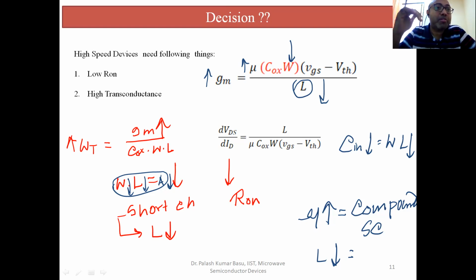And how to achieve the high frequency limit? You have to have a structure where you get a high mobility. But if you want a high mobility, you have to make sure it does not suffer any kind of collision. Very, very important. You need a high mobility where you avoid any type of collision. You can ask how it is possible, because my electron is flowing through a transistor, through a material, and the material has a lot of defects. You cannot have electron transport without scattering.